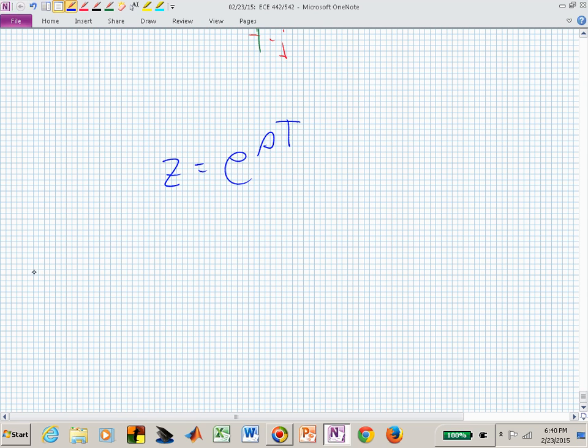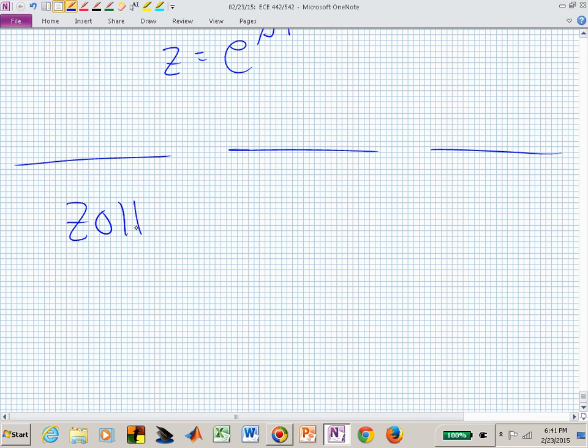Let's look at one more. We've looked at the zero order hold of a constant. We've looked at the zero order hold of a pure mass. This one was 5. This one was 1 over s squared. Why don't we look at something in between? Let's look at a pure integrator. 1 over s squared was 2 integrators. What happens when we look at the zero order hold of an integrator? Maybe we jogged before we walked. Let's walk with this integrator.